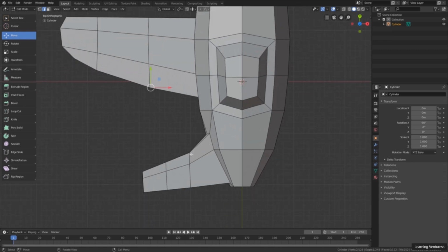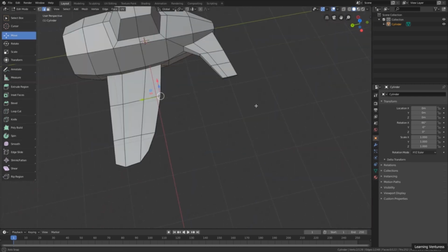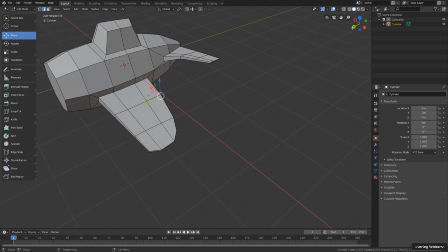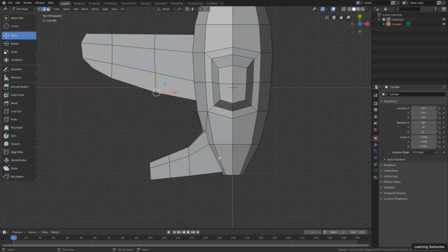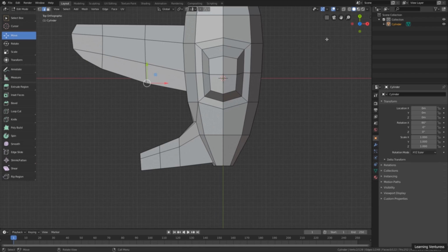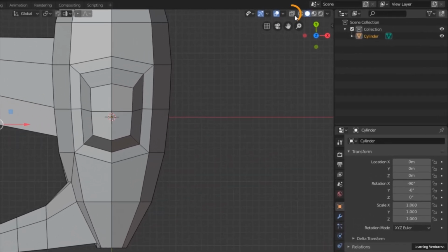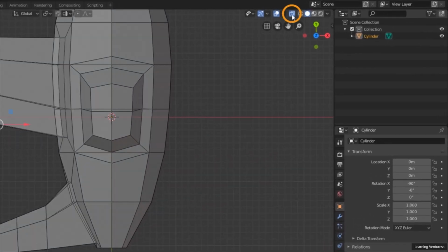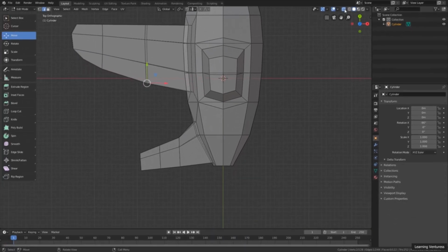But so that I can make sure that looking from the top view, I select both vertices, the one from the top and the one that is below, back there, I need to activate the transparent mode, the X-ray mode, by clicking on this button over here, okay? When this button is selected, whenever I create a selection window, everything that is inside this selection window is selected, even if it's behind the geometry that I am seeing, okay?